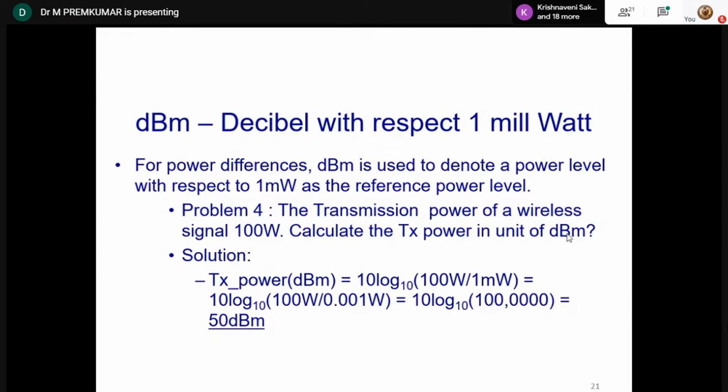If you want to convert to dBm, you take the given power in watts, divide it by 1 milliwatt, and provide the solution in dBm. You can provide solutions for any given application with respect to RF, either in decibels or in dBm, to find out the system loss factor, insertion loss, or isolation loss, whether it is the phase shifter, the switch or the low noise amplifier which you are going to consider.